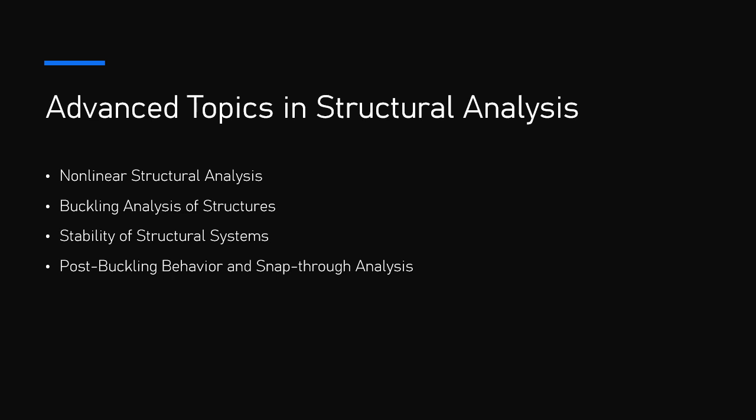This is the most common iterative method for solving nonlinear equations. In this method, an initial guess for the solution is improved in successive steps by linearizing the system around the current solution and solving for the next iteration. Modified Newton-Raphson method. An extension of the standard Newton-Raphson method that modifies the tangent stiffness matrix to improve convergence.